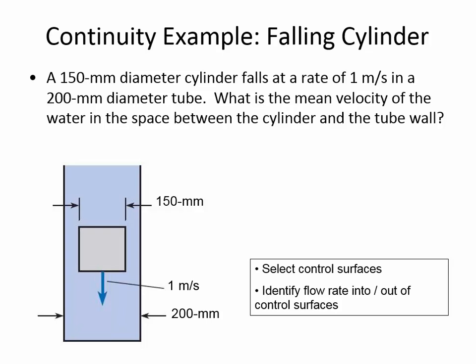You know, it's just banging in and changing directions. But if you only have it at an angle, if you're only asking the jet of air to change its direction a little bit, it requires less force. And so this 30-degree deflector piece, it's not going to generate much force because it's not really changing the velocity all that much. It's just changing it from straight up to 30 degrees from straight up.